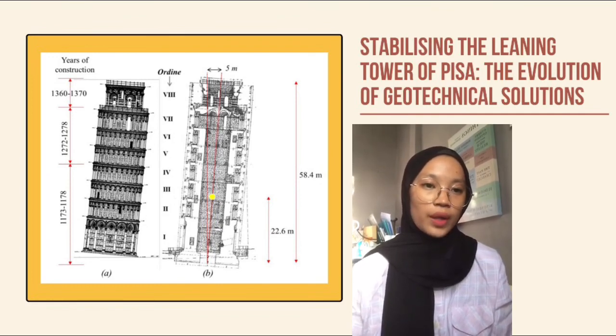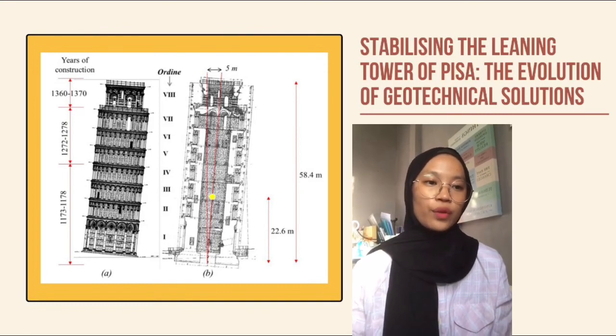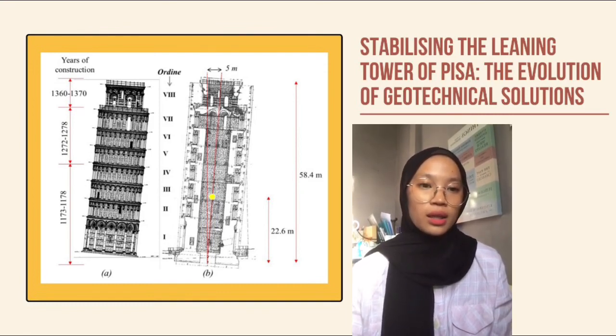First is the north-facing slab being strongly advocated by Professor Leonhardt. Second is drainage of the marine clay on the north side by means of electro-osmosis. Third is drainage from the intermediate sands beneath the north side by pumping from wells.